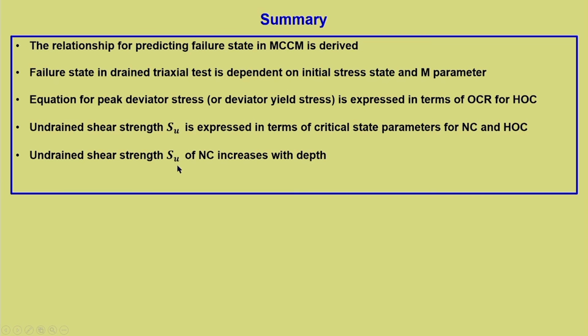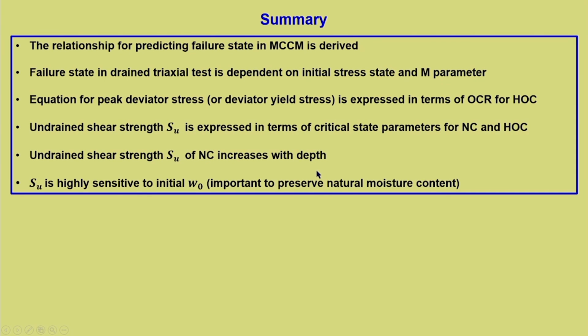Undrained shear strength SU of NC increases with depth, that we have shown. SU is highly sensitive to initial water content. So, it is important to preserve natural moisture content. That is all for today's lecture.